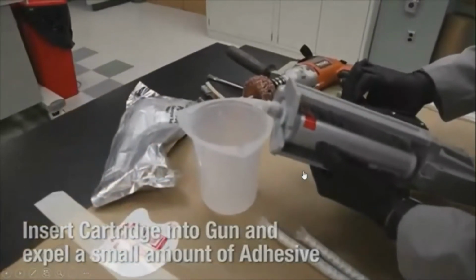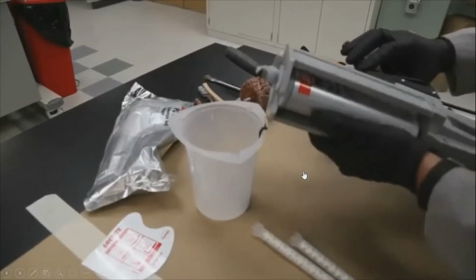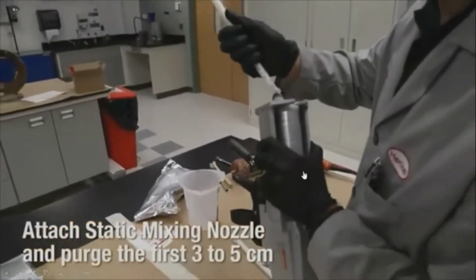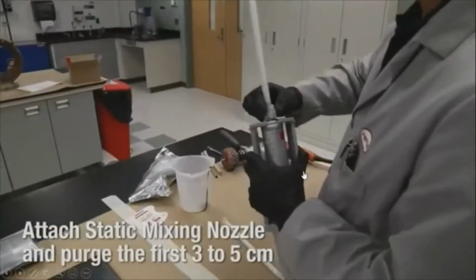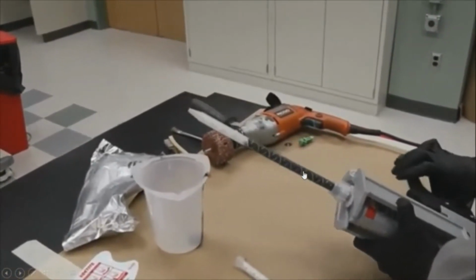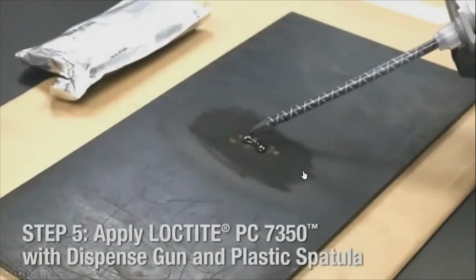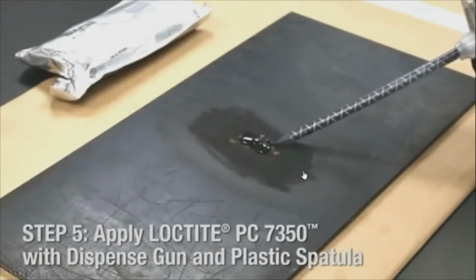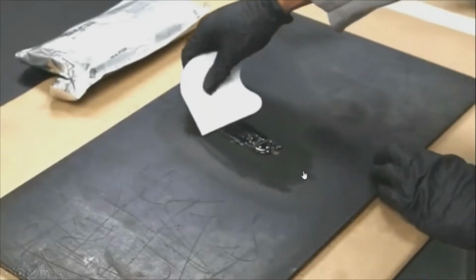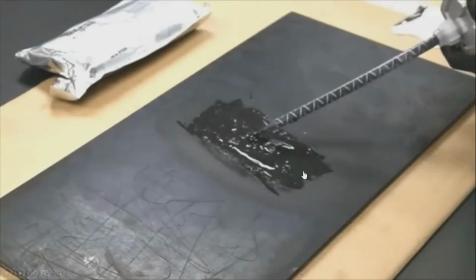For this application, it has its own applicator gun and also a mixing nozzle that comes with the product, and I can say it's important. Using this applicator, we can make sure that our mixing is in the correct ratio, because sometimes if we do manual mixing, we might accidentally put a lot more resin or a lot more hardener inside the system, which might affect the performance of the product itself.